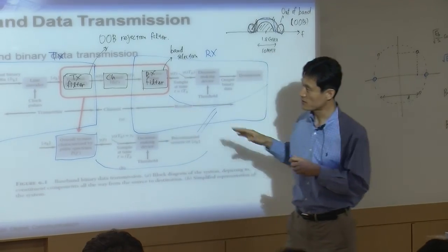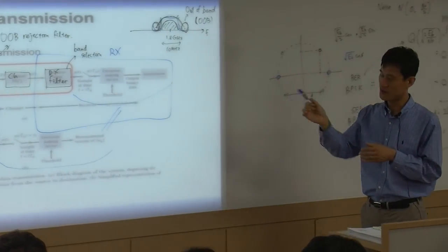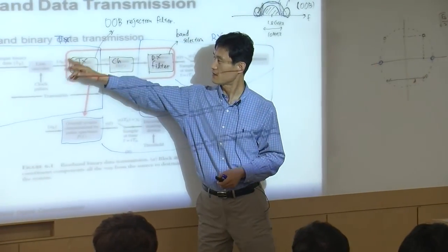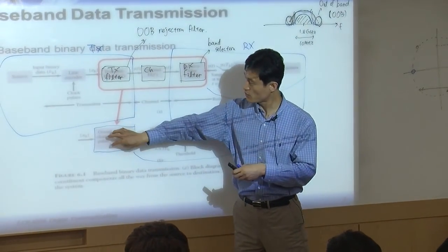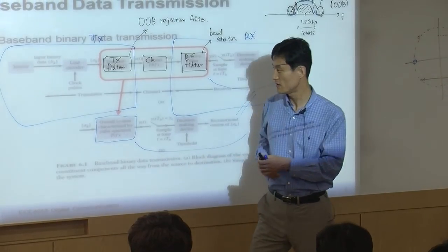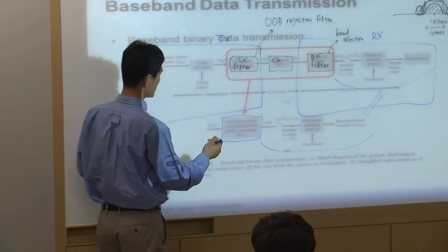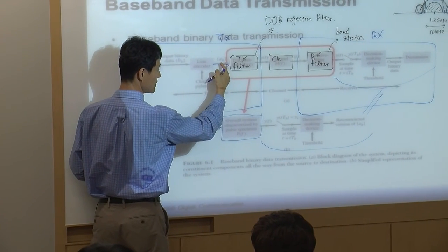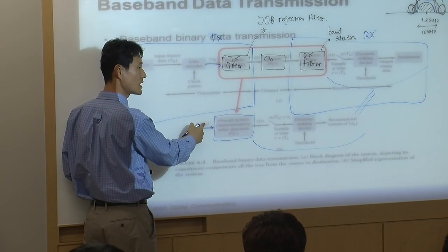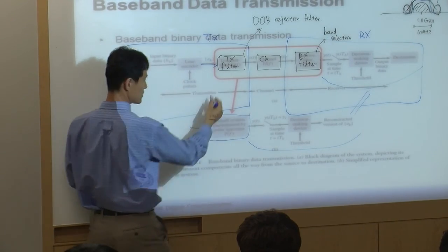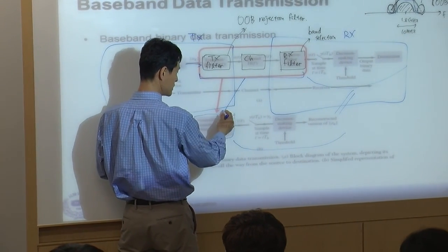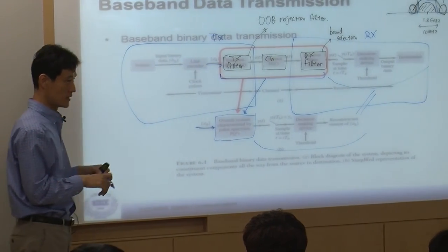Just look at this block diagram and look at everything in a sequential manner, and just put these 3 together and make it one. So this is a simple model, right? Input to this block is this one. So this line and this line are the same. So put these 3 blocks, group together, and replace them with this one.